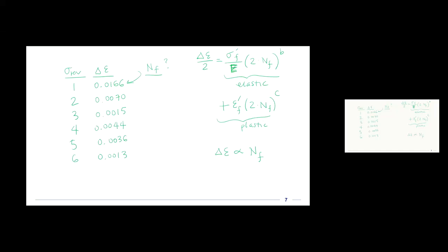What we need to do now is put in what we know. We just calculated this delta epsilon. We can look up these material properties: the failure stress in low cycle fatigue, the modulus, these coefficients, and epsilon F. Once we have those, we can solve for the cycles to failure that correspond to the change in strain we calculated. There are a few subtleties in calculating B and C, which can be a function of a strain hardening exponent, given in the textbook in figure 8.14.